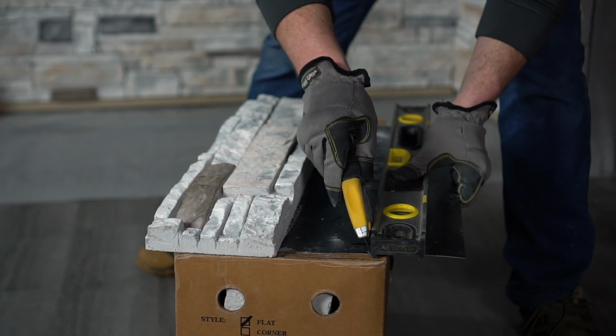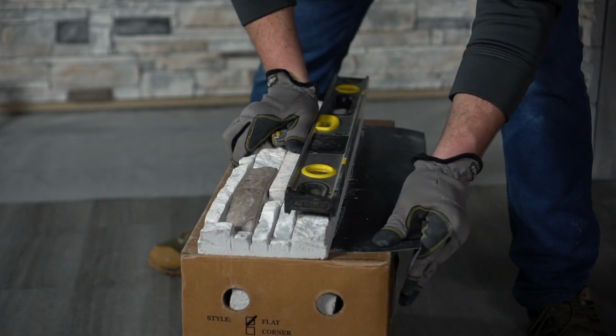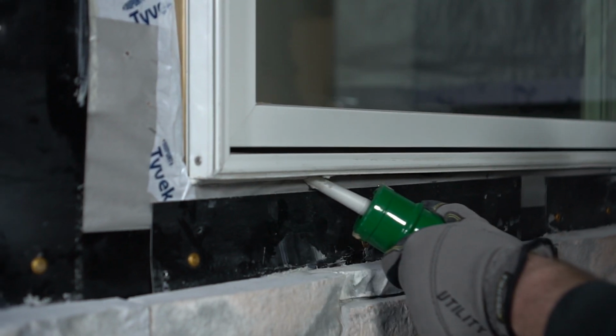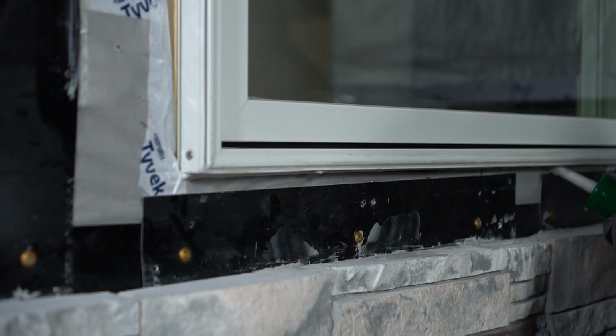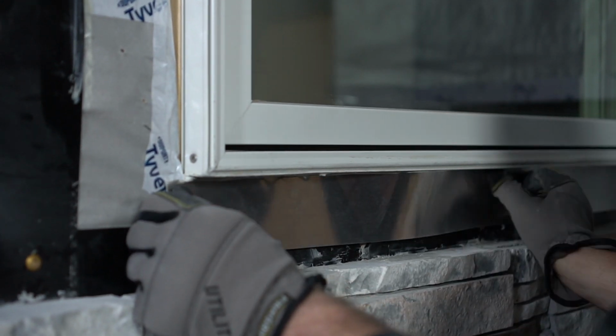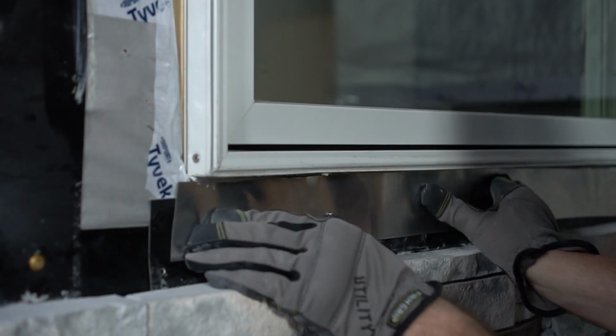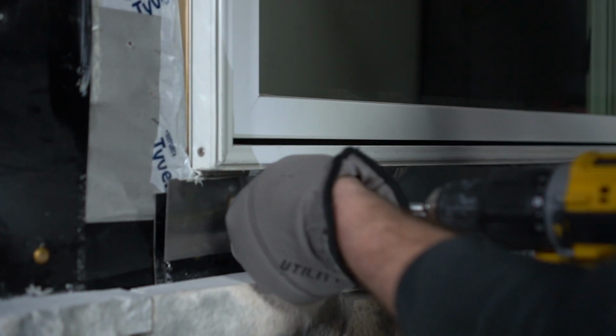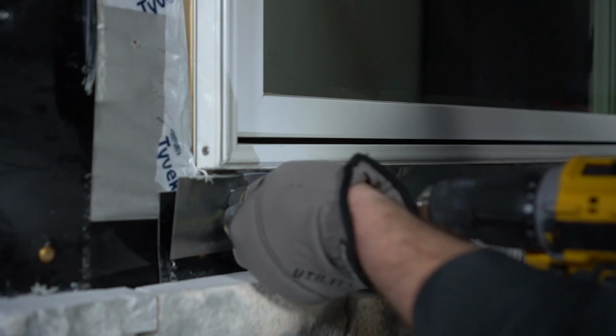Trim flashing on second to last course under window so flashing adjoins against the bottom edge of the window. Apply a bead of sealant to the edge of the window. Install unpainted aluminum flashing, covering all exposed areas and bedding the top edge into the sealant and securely fastening flashing to the wall. This will be the base for the adhesive that holds the modified panel in place.